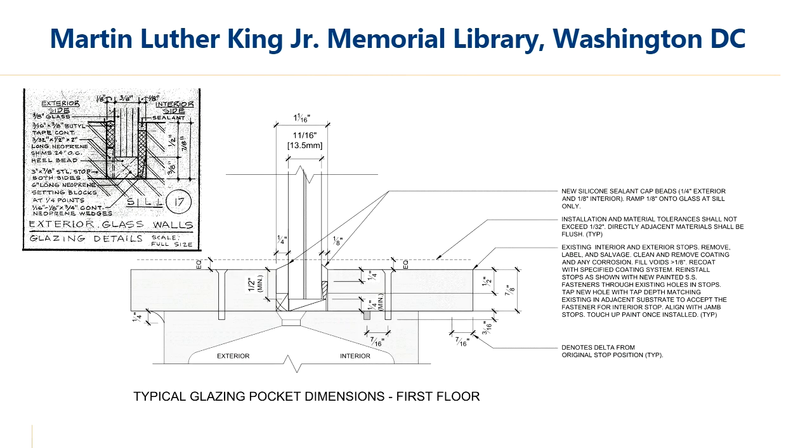As Becky discussed, glass isn't used alone. So how did those final selections affect the iconic Miesian steel frame? The original glazing pocket dimension of 5/8 inch was increased by 5/16 for the bigger glass, and increased again by 1/8 to provide a more durable exterior silicone seal. We ramped that seal slightly to promote drainage, and ramped the interior seal to try to minimize the visible impact of that exterior ramp. The decision was made to retain the original stops or replace them in kind, rather than decreasing them in size to match the original offset. This did result in a chamfer at the inside corners of the stops.